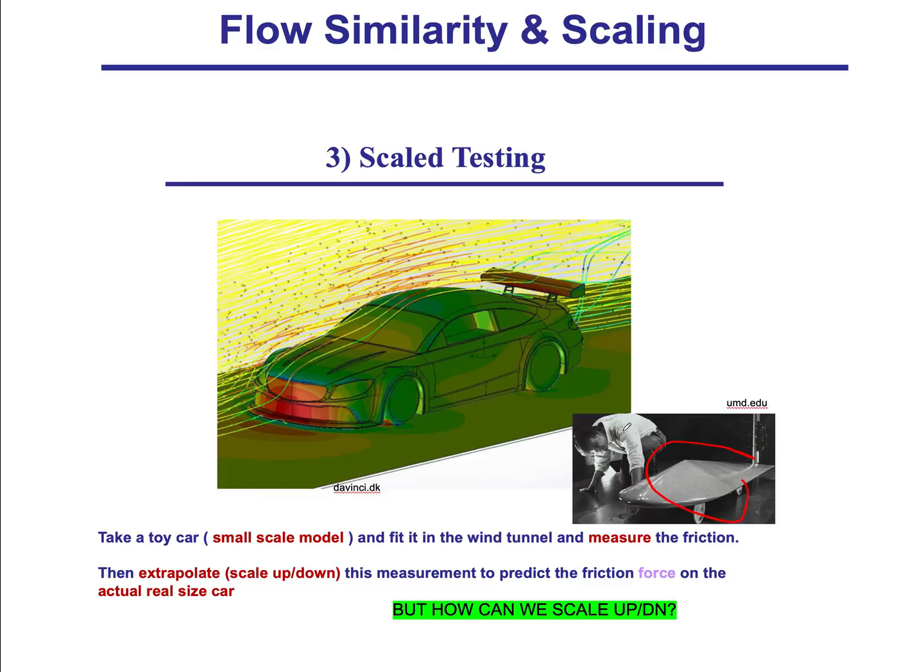So you can see it's a scale. Here it's a bad example just because these have to look exactly the same. But imagine that they're exactly the same shape, but of different scales. So that's the point here, that we have different scales. Because it's cheaper to make, we can make it out of wood, stick it in the wind tunnel, and get, let's say, a drag force of 20 newtons.